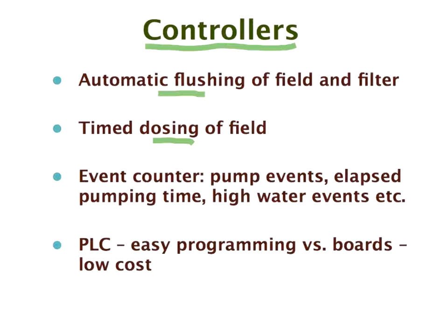You want an event counter so that when you come back you can check how often the pump went on, the amount of pump time, and if the high water alarm went off, how often it went off, and you can check the record of what happened.